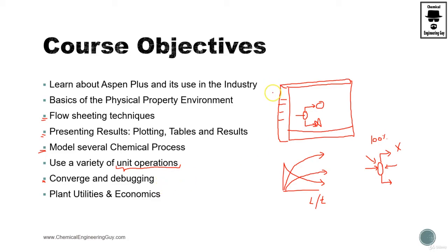It might be something silly, such as not having prepared the physical property environment, a line missing in the title, or maybe you typed CO2 but are actually using carbon monoxide, and of course the reaction is incorrect. Even though you think you're using CO2, you are using CO, so of course there's going to be a mass balance error, energy balance error, stoichiometric error, and so on.